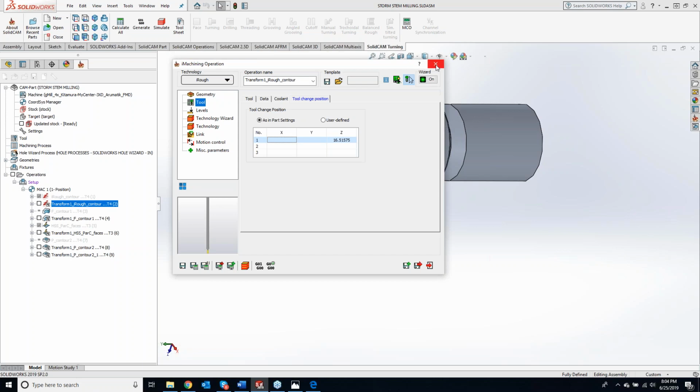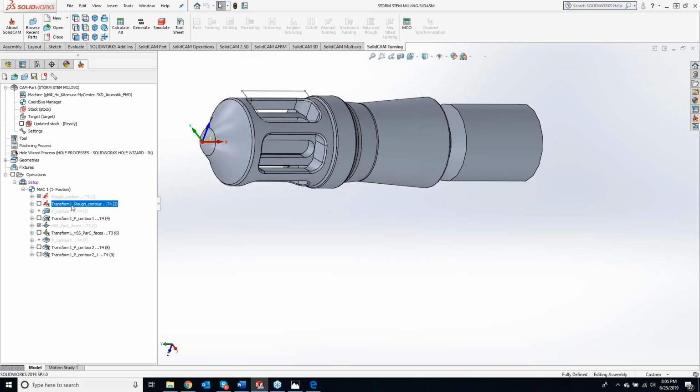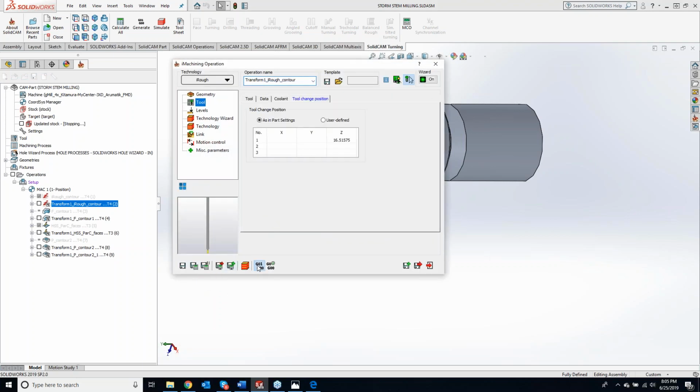Now, since we're going along the lines of inserting Gcode into a program, let's say that after a part is halfway done running, you want the spindle to go up in Z, and you want the table to come towards you and do an M00. What you can do is actually insert Gcode into your list right here. So I'll open this operation back up, and I'll show you a little example of this. We'll just do a Gcode.